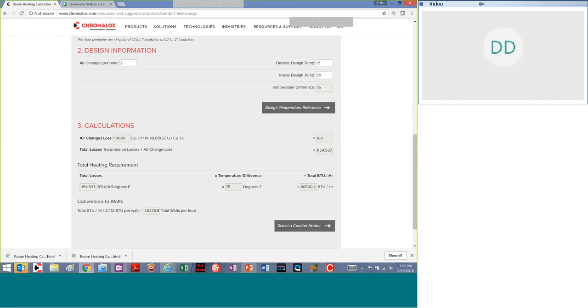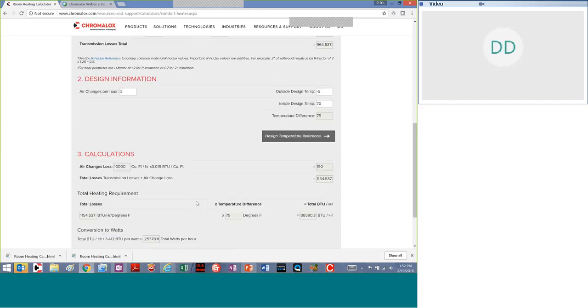Hey, you got a second? Well, let's see what size you need. Let's quote you an item. That's really easy. And something we're going to talk about strategy in a minute. Another side of this is I live in Colorado. -5 is a bit of an extreme. Maybe they add a little more insulation. Maybe not. Honestly, you're not going to be in there when it's -5 out. So let's use 40. Now we're down to a 10 kW heater. And this becomes part of educating the customer on where you want to set your goals. And explaining it to the customer, they'll make the selection.